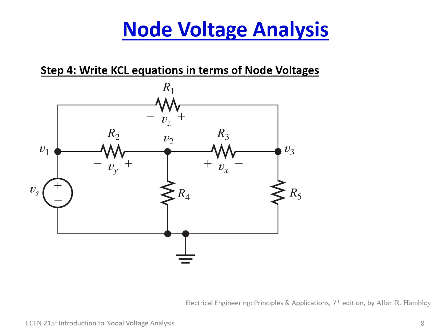So here's our circuit, and we have VZ, we have VX, and VY, which we obviously also know in terms of V1, V2, V3. When I usually do this, I don't usually do step 3. I sort of skip through it because I instinctively already know that the voltage across R1 is V3 minus V1. But it's a good thing, until you get into that practice of knowing the voltage drop across R1 is V3 minus V1, that you probably write that. But it could make your problem a little messy if you do that.